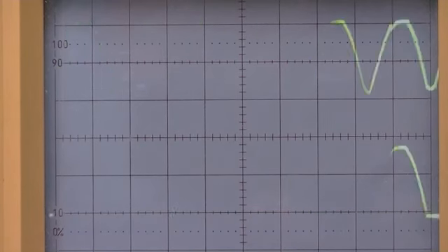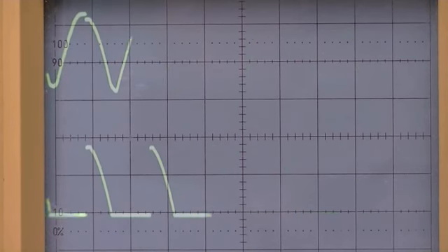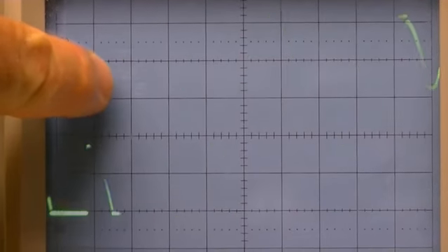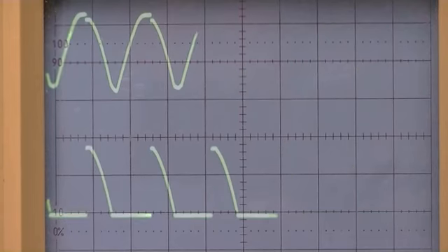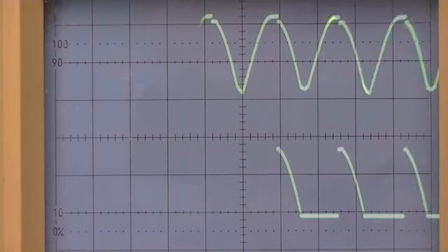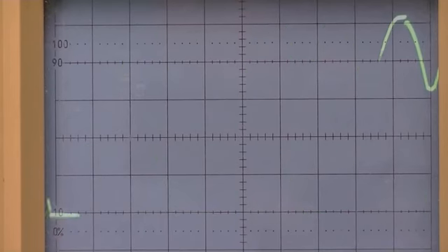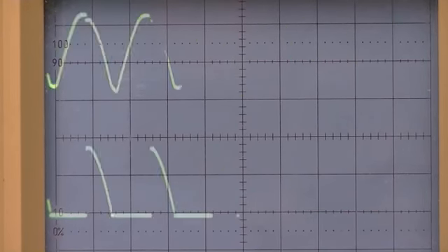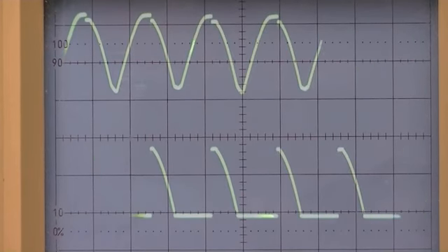The secret is that you're going to detect the 0 crossing pulse, which in this case is here or wherever. Then you're going to set a specific time delay before you trip on the triac or SCR based on a potentiometer that's connected to my Arduino Nano.